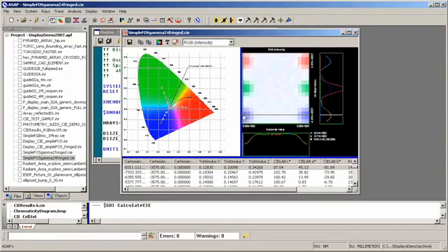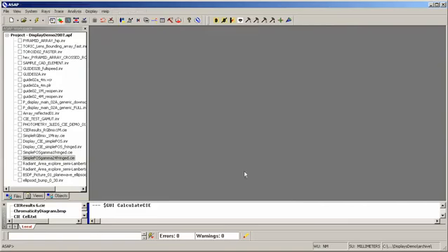And this is at limited resolution, but it's a very real kind of analysis that you might do for a monitor. Typically, this would be used to look in the mixing region if you have a light pipe that is mixing red, green, and blue LEDs. And if you're using side-emitting LEDs, then this may be actually happening right behind your front of display, but you're using the side emission characteristics to do the mixing. And in that case, you might actually have to look at these kinds of results around the arrays of LEDs. So that's a summary of colorimetry.